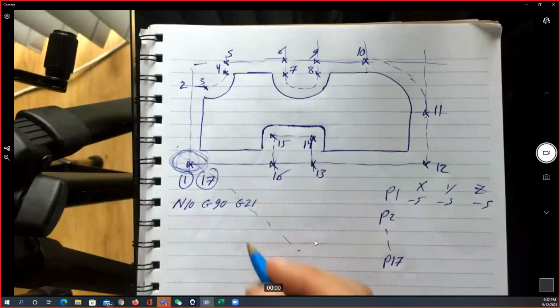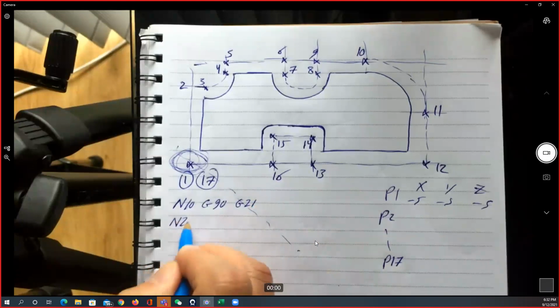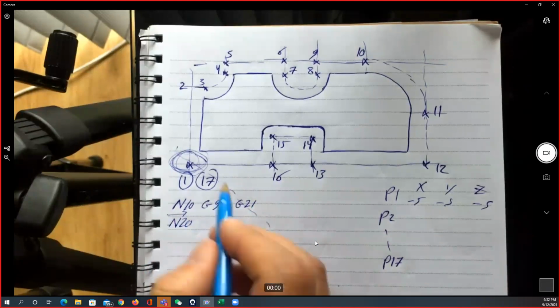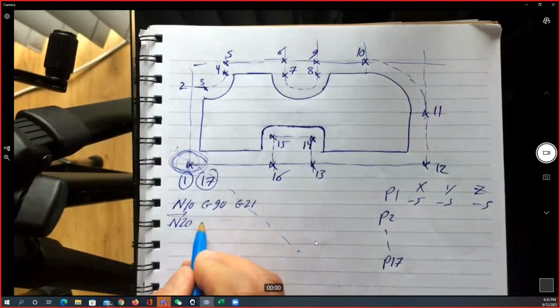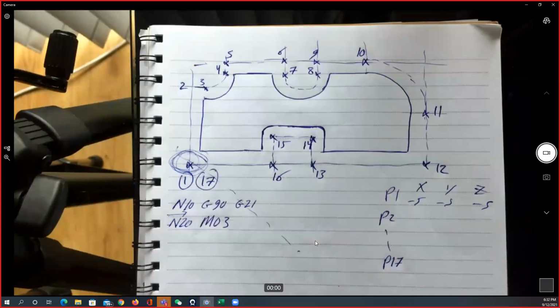And go to the second line, line 20. We said that if I get to 10, 20, then that means I can insert here 9 extra lines. If I have a mistake, I can delete this one and put another one down there. So, and this one again to write down M03. By the way, we can put the program number.